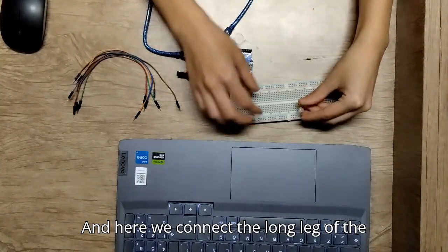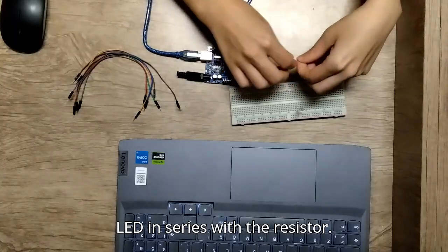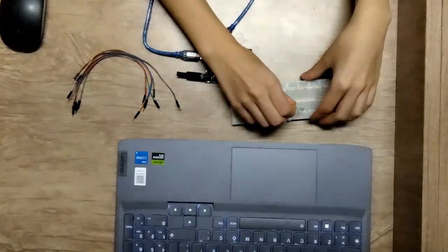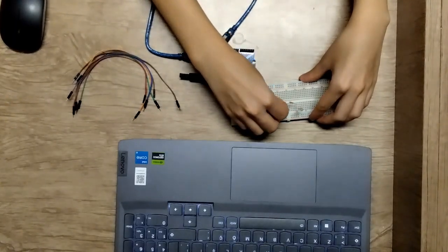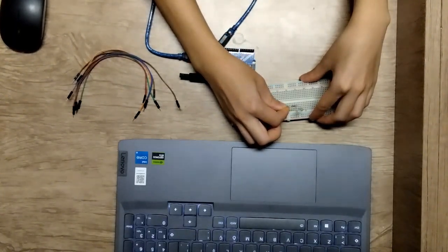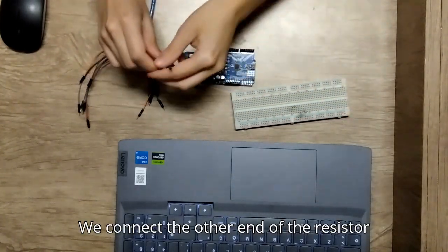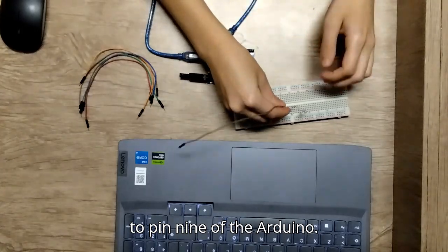Here, we connect the long leg of the LED in series with the resistor. We connect the other end of the resistor to pin 9 of the Arduino.